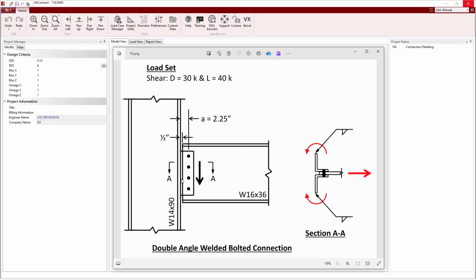The welds at the support are designed to resist the eccentric shear loads using the Instantaneous Center of Rotation method to determine the eccentric weld group capacity. The C coefficients for eccentrically loaded weld groups are included in the detailed reports.